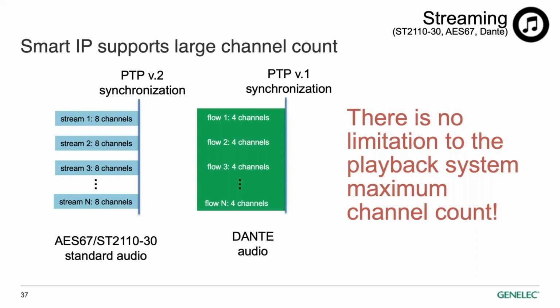You can have as many loudspeakers as you like, provided that you carefully design the network to cope with the resulting traffic, and you have enough power feed from PoE plus capable switches. So this is, in short, what kind of approach we have from Genelec towards network audio for the AV install market. And the Smart IP systems are available.